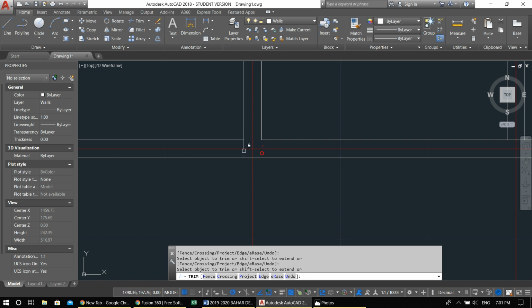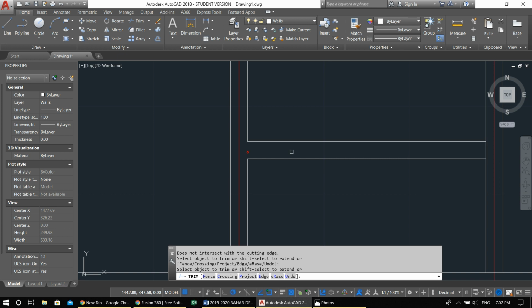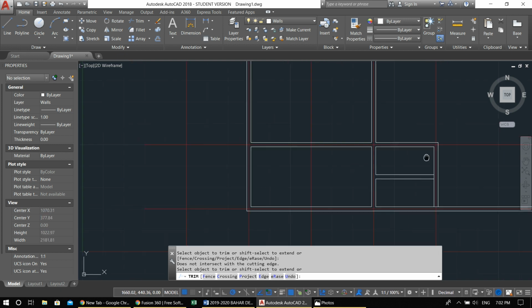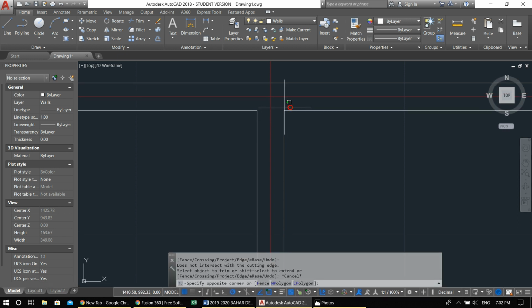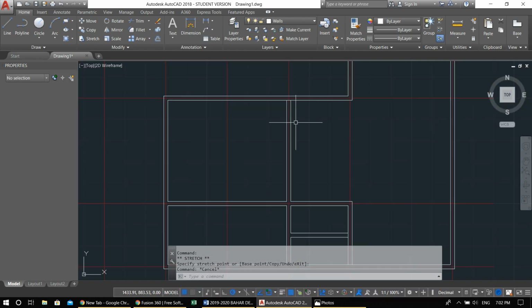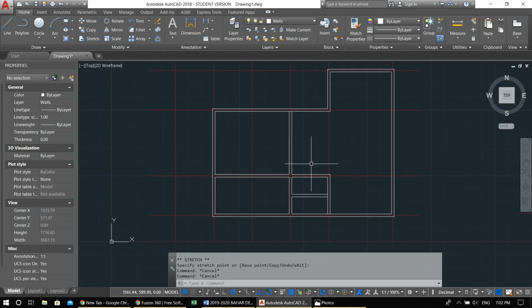Okay, so for now, just go around, practice trim, TR, enter. Some people will kill me for this, but anyway, there are better commands, but this is for basic beginners. Anyway, let's go around. Let's see if we don't need to trim this, because if you look at the drawing, you actually have to. Even this one, I made a mistake. It was not necessary. So if you want to continue this line, you can always pick it and move it over there. Okay, so this looks okay now.